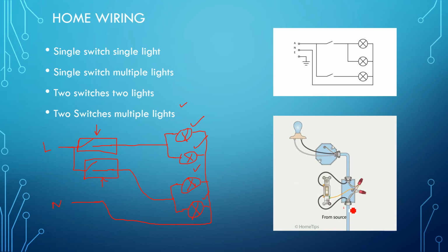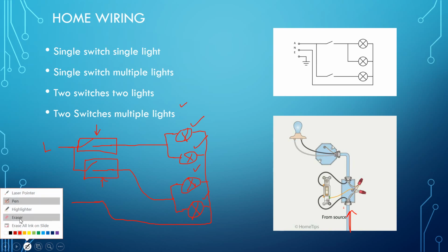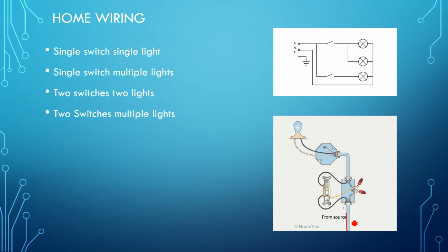And this is our wiring. For example, as you can see from here, we have three wires coming from here: one is line, one is neutral, and one is earthing. So where will we put the switch? We will put the switch in our line. The line, this black one, is coming here, passing through the switch, and then coming in this conduit, and then connecting with the phase terminal of the light.